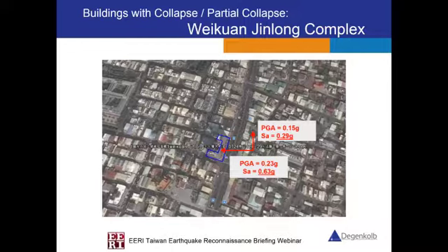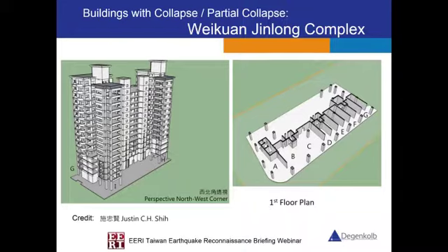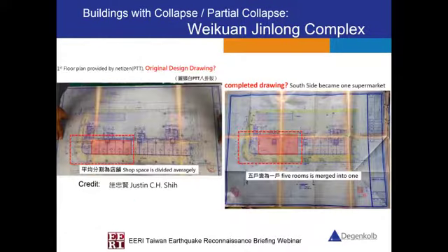Around the structural period region is about 2 times bigger than the north-south component. One of the local engineers helping demolish the building after the earthquake did a quick analysis of the building, based on limited information and drawings, or using Google's Street View to construct a model. From the drawings he got, he found that there were some modifications between the original drawings and the as-built drawings. Basically, a couple of walls were actually not constructed.